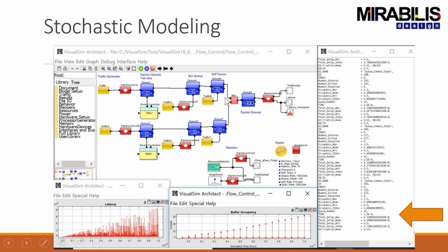So for example, the register for this one could be egress. So then all I have to do here is go and look up that register and know what the value is, right from the script where I've written the logic for the arbitration, and then be able to determine which queue I need to trigger. So rather than having wires, or rather than having to send a message, get an acknowledgement back, then the data, I just do a lookup, and then I can quickly get that information.